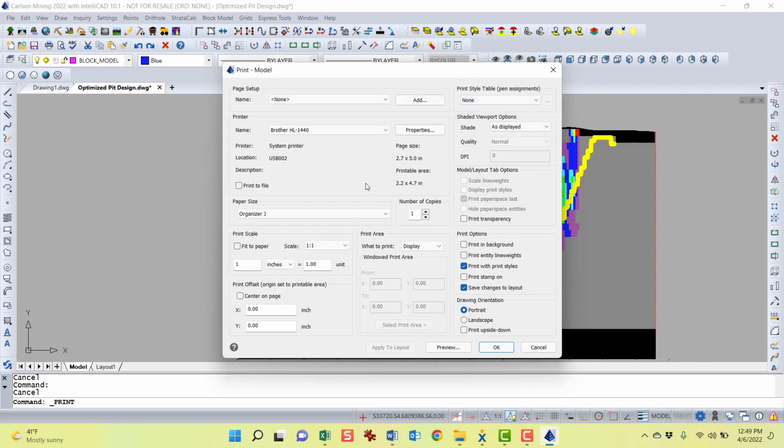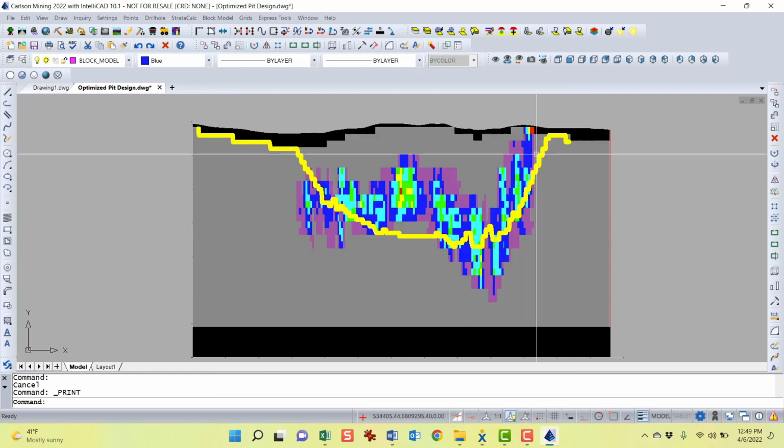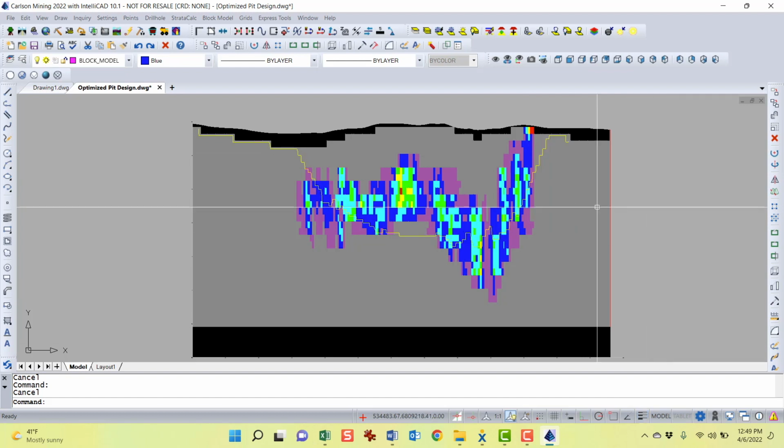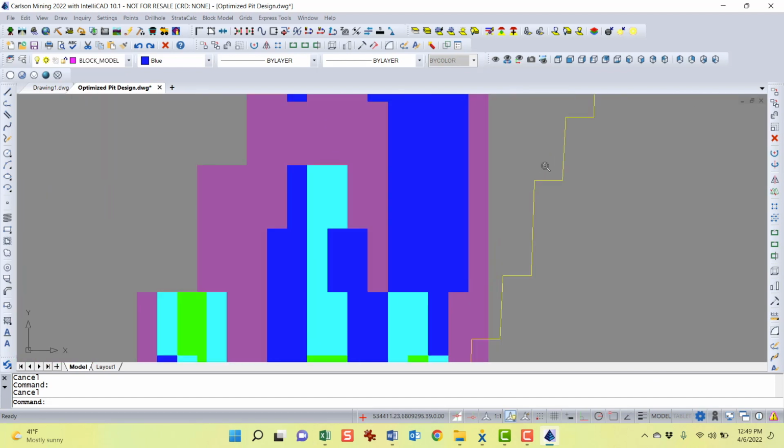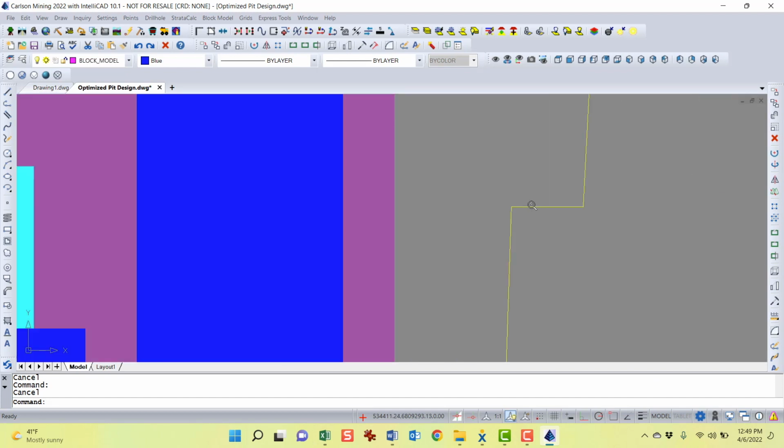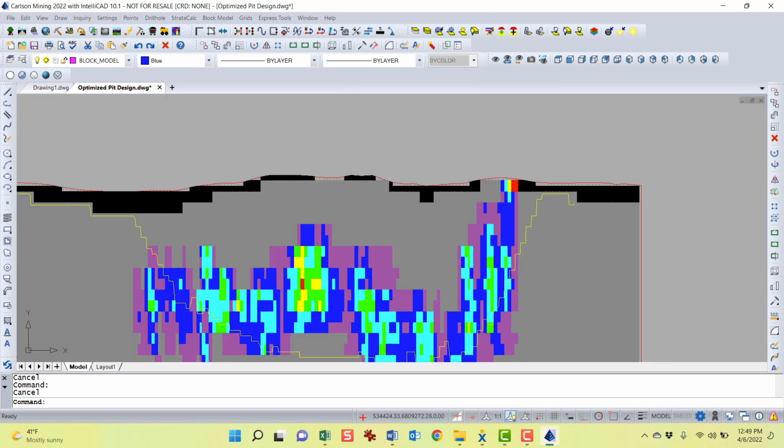This is a little different than the AutoCAD plotting window. I know it's there in AutoCAD, but in IntelliCAD, I guess it's right there. It just allows you to plot the line weight. But that one's a little bit too thick, so I'm going to drop it back down. Or it's a switch, you can just turn it off altogether. So the entire drawing has no line weight active, and they're all just shown as the smallest increment, which actually is a line weight, a line thickness or weight of 0.